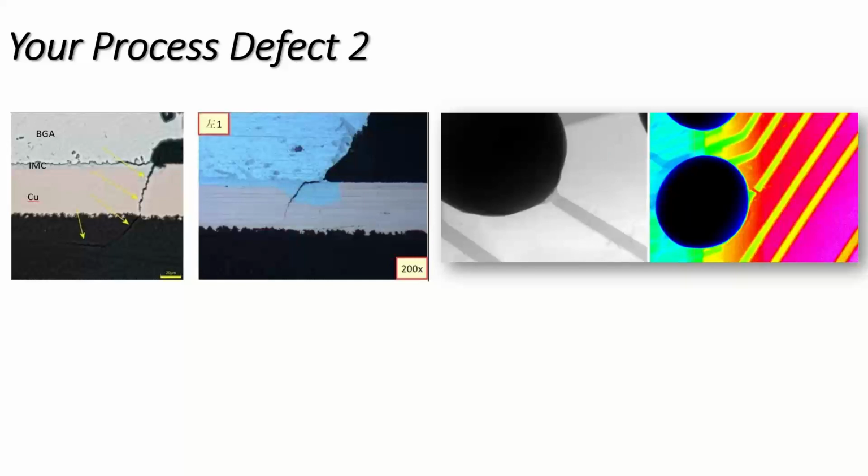This was a device which was thermal cycling because of the heat generated by the actual device operating, and in time it was literally wearing out. And this was right on the corner balls, where on a package you tend to find the corner balls are perhaps more susceptible than any other to mechanical strain. So there's a couple of examples. I still think it's vibration or drop testing which the customer has a particular problem with at this moment in time.